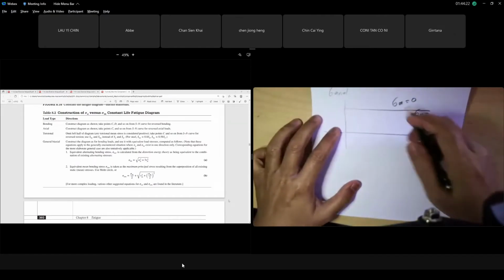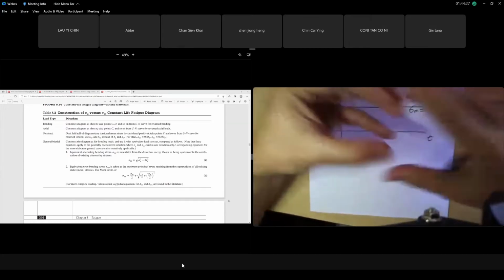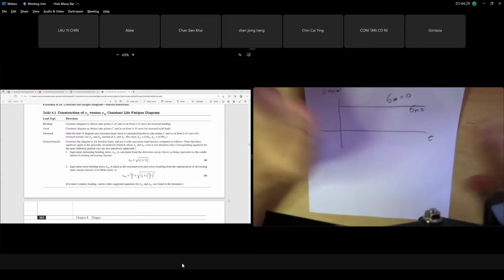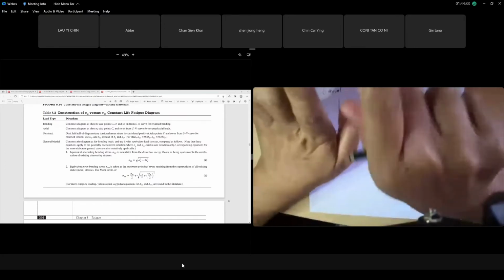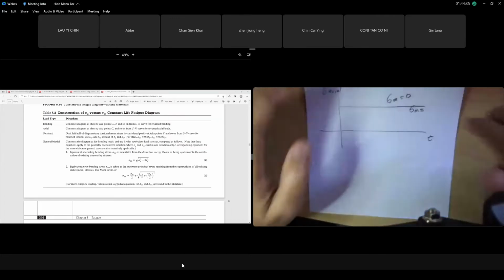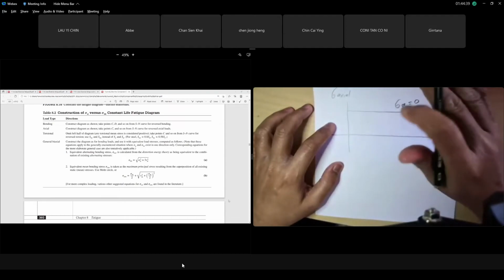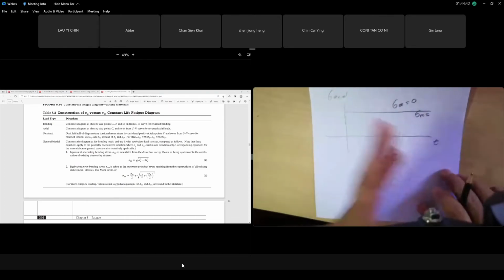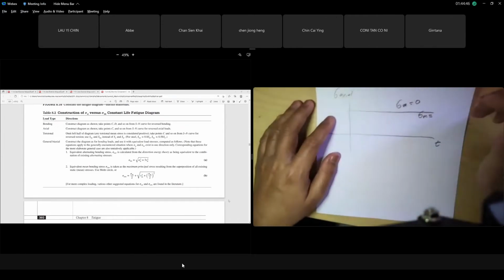And axial, okay, even when the shaft is rotating, the axial stress along the shaft remains constant. Same like torsional stress. Remember, for the torsional direction too, it remains the same. But at the groove, at the notch, we don't have torsion. Remember, torsion is only between A and B. Before A, we don't have it. Since the groove is before A, 20 millimeter offset to the left, before A.